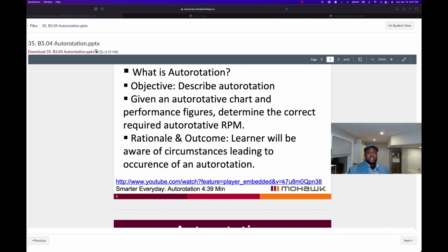The next factor we want to discuss is density altitude. Density altitude affects autorotation. At higher density altitude, the helicopter will have a tendency to have poor engine performance as well as poor aerodynamic performance. A higher density altitude will generally require slightly higher airspeed to get a successful autorotation.